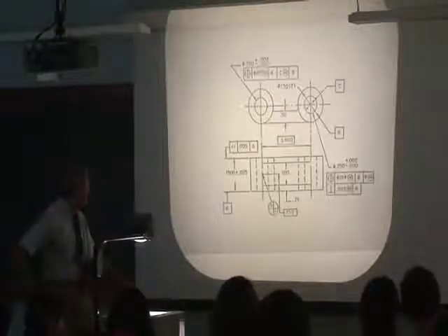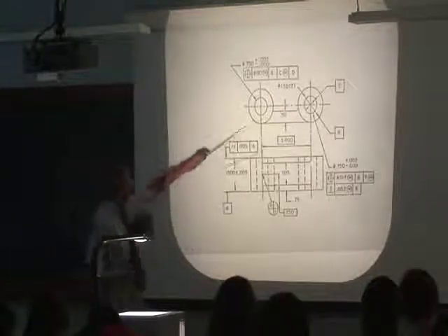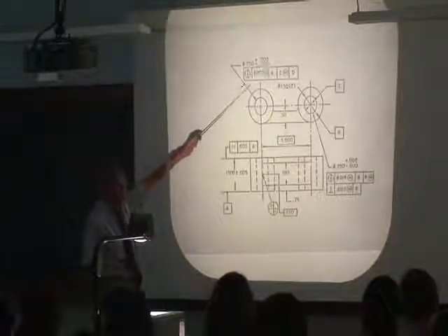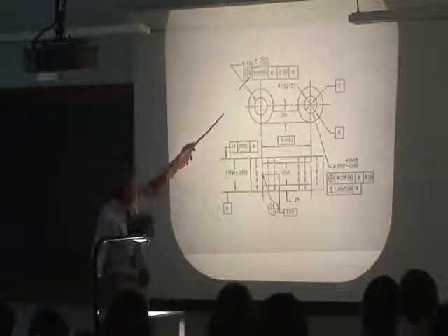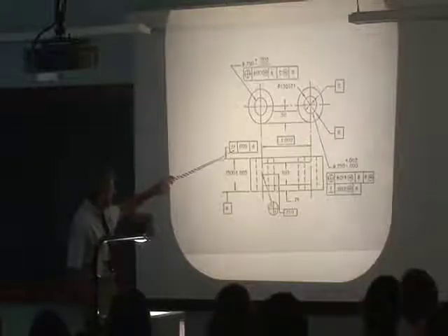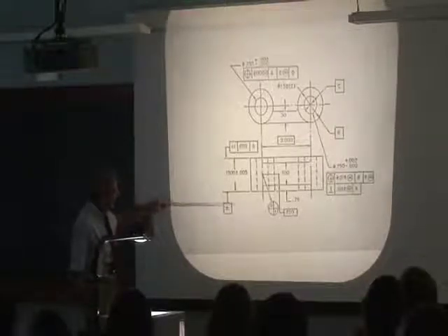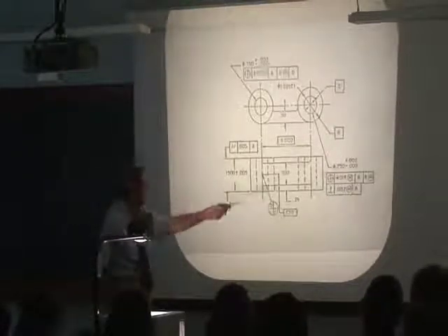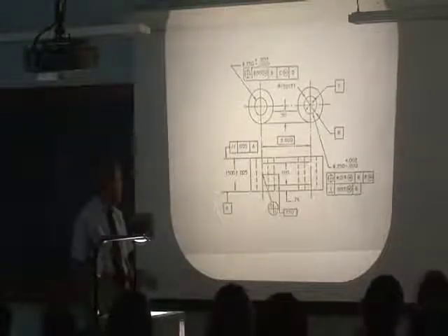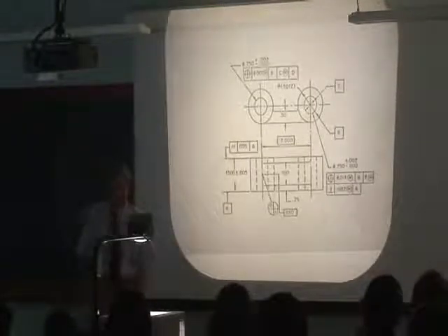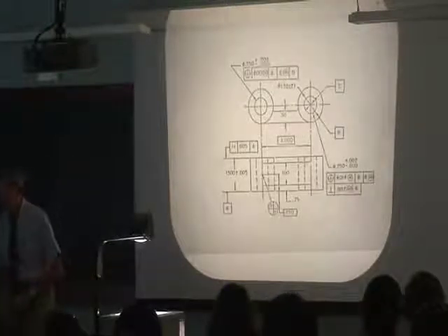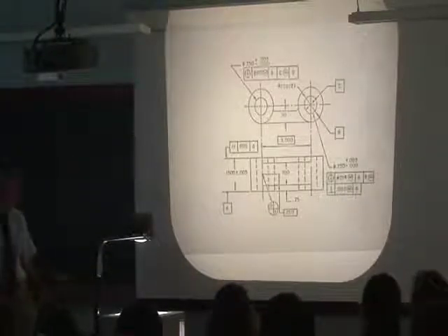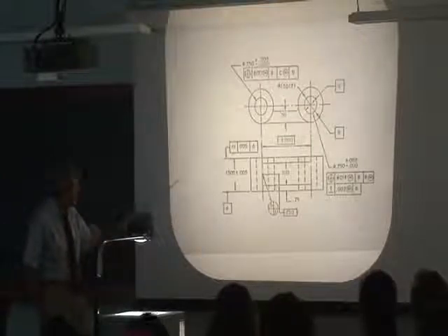This is a geometrically toleranced part, and it has lots of symbols that many of you may have never seen. This is a position symbol, and this is a parallelism symbol, this is a datum designation, this is a datum target, and so on and so forth. And these have very, very precise spatial meanings. And they clear up almost all of the ambiguities of drawings. But they take a lot of learning.